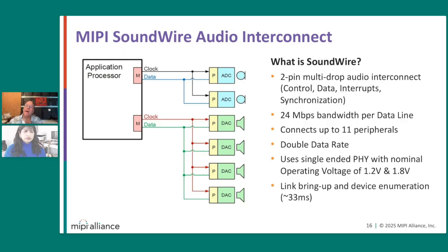Classic also supports a finer grain trade-off between power and bandwidth. So it uses a 2-dimensional allocation scheme like SONET. So you can change the number of columns per row as well as the row rate, again, synchronously, so that you could have seamless audio flow while you're making these changes in bandwidth, but it's finer grained than SLIMbus.